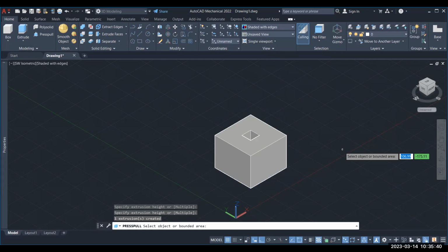Very specific. You can generate this kind of object with extrude also. For that, what I need to do? First, I need to generate a complete solid. On that, I'll fix one shape, the cross-sectional shape. What is the cross-section shape of the hole? Then I'll fix it. From that, I'll remove the material. So too many steps. Instead of that, you can do like this.